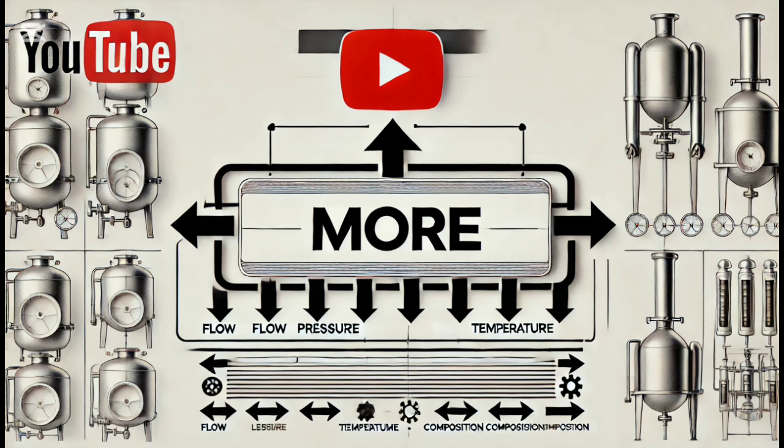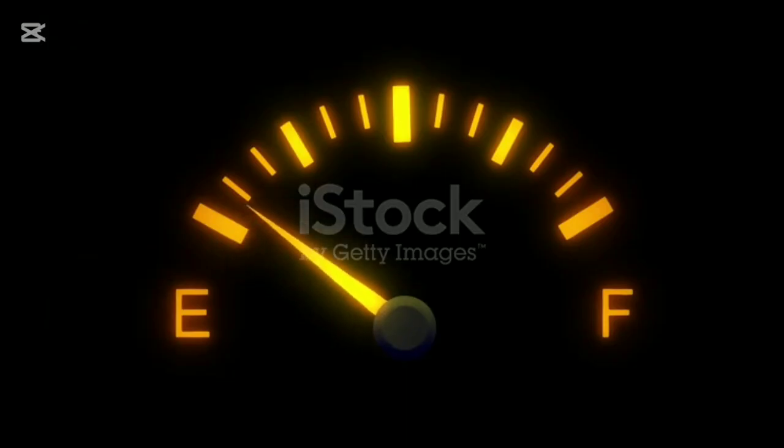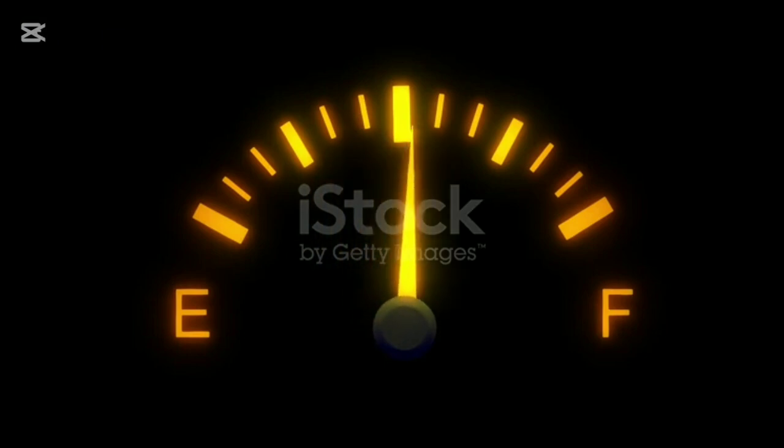We will apply the guide word more one by one on all these parameters. More flow could result from an oversized pump or incorrect valve operation. Deviation: more flow into a gas absorber column might cause flooding or operation inefficiencies.